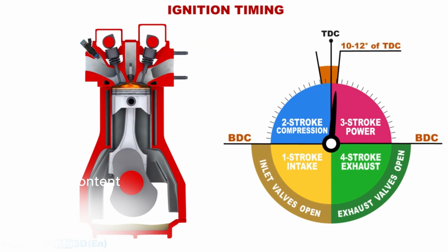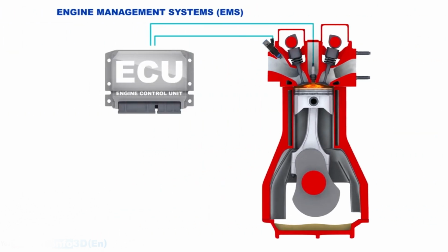For maximum engine efficiency, the piston must be within 10 to 12 degrees of top dead center at maximum gas pressure. It means that the ignition system must start in advance. The moment at which the spark plug fires is called the ignition advanced angle. The optimal ignition advanced angle is determined by crankshaft speed. The higher the crankshaft speed, the earlier the spark plug must fire. If the crankshaft speed is low, the ignition advance angle should be closer to top dead center.